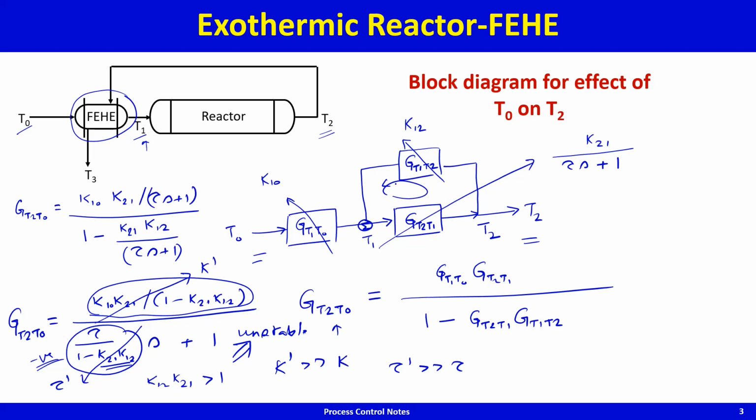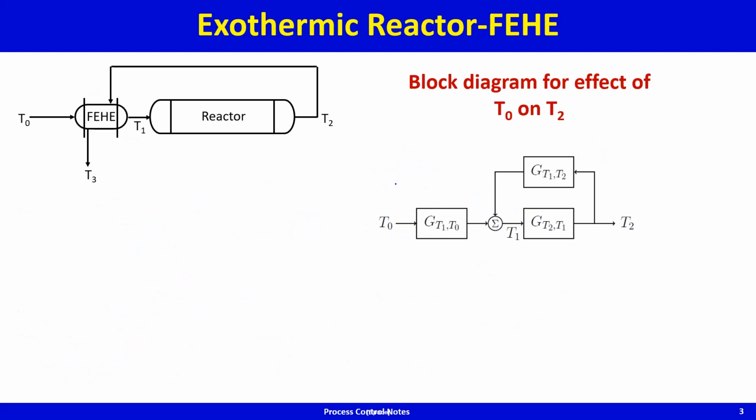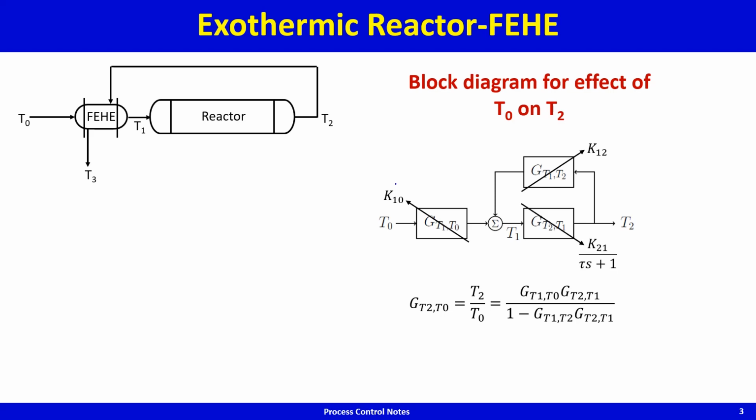So this is the block diagram. The transfer function, and if I assume instantaneous dynamics of the heat exchanger and first order dynamics of the reactor, then the transfer function simplifies to this, much larger gain, much larger time constant.